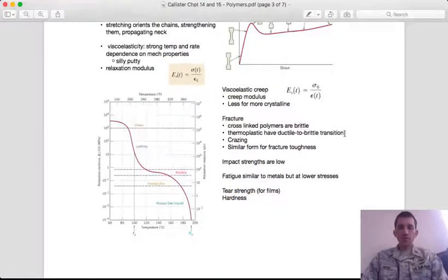And this can occur over a very narrow temperature range, right? Anyone who's ever gone out in the snow and played with, say, a plastic toy, as a child or your own children, some sort of a truck or a shovel or something, has found that it's much more likely to crack when cold than when it's not. So polymers have a ductile to brittle transition that we can actually observe in our everyday experience.